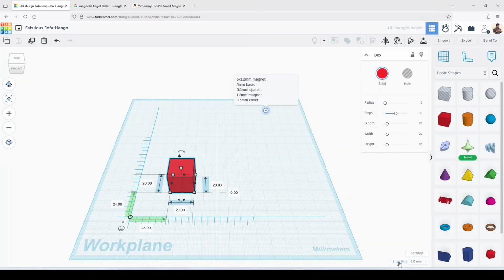We'll also make sure that the snapping grid is set to 1mm. So every time you move, your stuff is going to snap by 1mm, as you can see over here. The ruler actually has a very interesting feature. There are two modes that you can use. One of them is called use midpoint. So right now, when you highlight it, it says use midpoint. It's actually using a different mode. So the different mode is called endpoint.